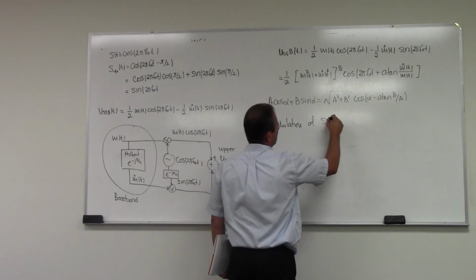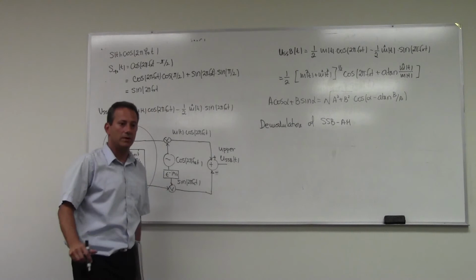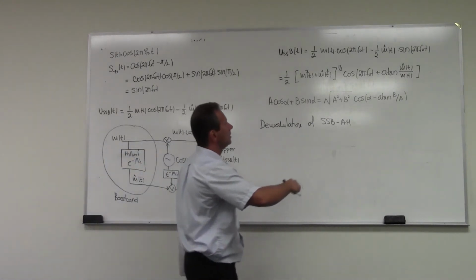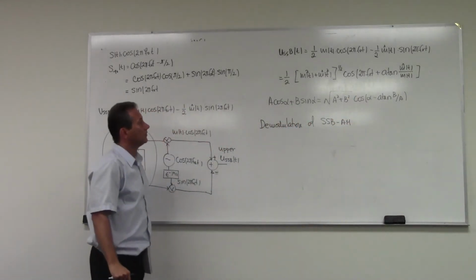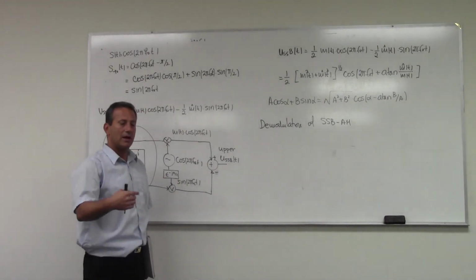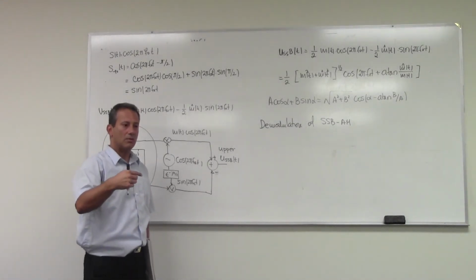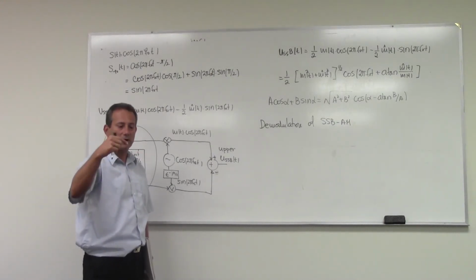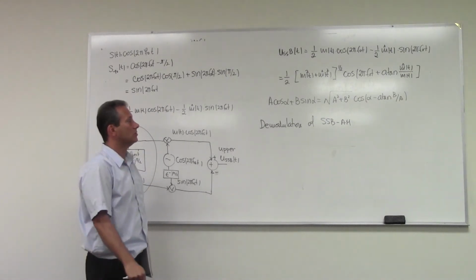Single sideband AM is demodulated coherently, meaning that to be able to demodulate this, you have to have a local carrier with the appropriate frequency and phase. Now, there are difficulties associated with generating local carriers, and in practical systems using single sideband modulation, it is not uncommon to send the carrier along with the signal itself, so that you don't have to generate it locally. You can use the one that you receive, amplify it, and use it for demodulation of the signal.